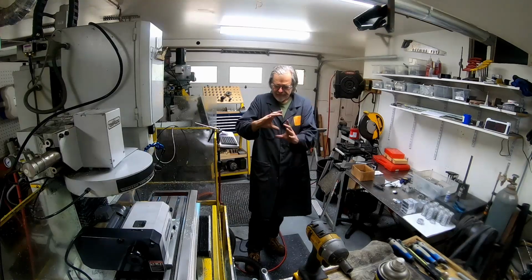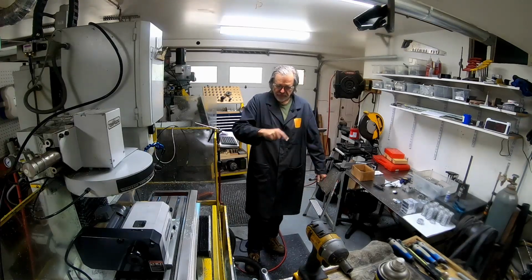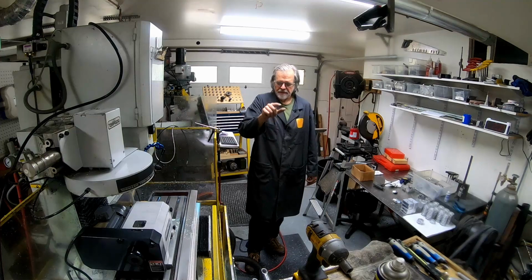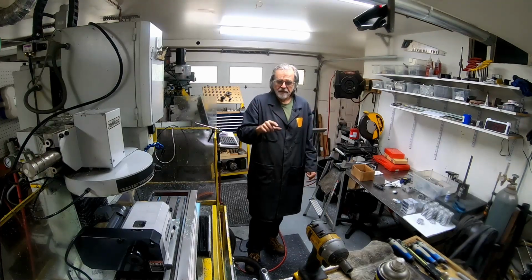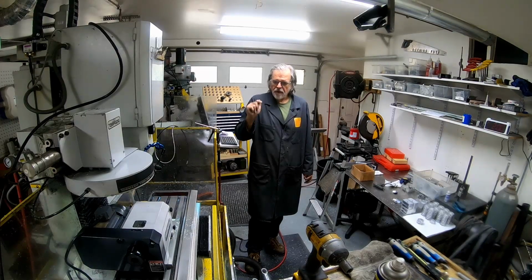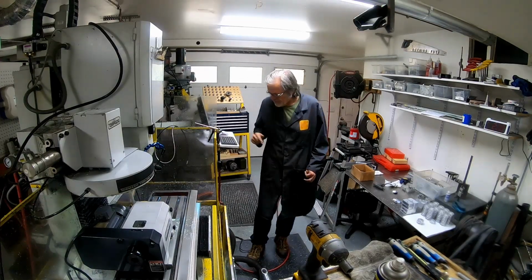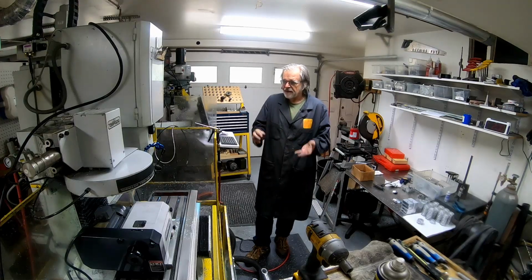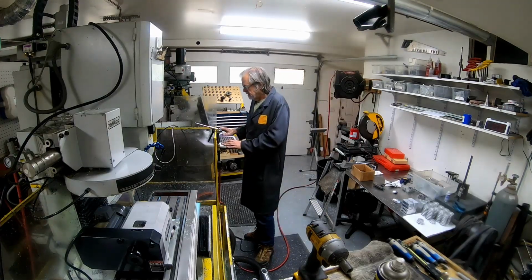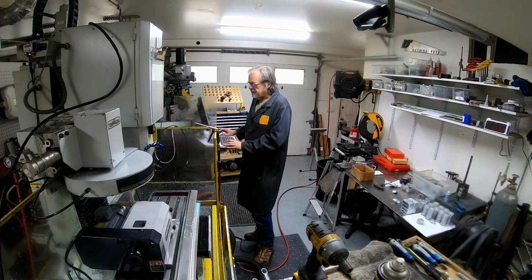There's like this array of like 12 different or 8 different, I think it's 8 different orientations where you can set the offset for the tooltip, and I didn't have the offset set correctly because I tried setting up the machine before running the G-code, and the G-code set up the tool number, which I totally forgot.